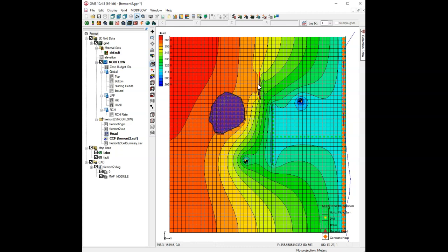And you could calibrate the hydraulic characteristic until you got the head differences that you observe in the field, but in any case, that's working properly as a horizontal flow barrier. And so yeah, we've simulated, we added a lake and we added this fault using the GHB, general head boundary package, and the horizontal flow barrier package. And so that gives us a nice introduction to these two new MODFLOW packages.